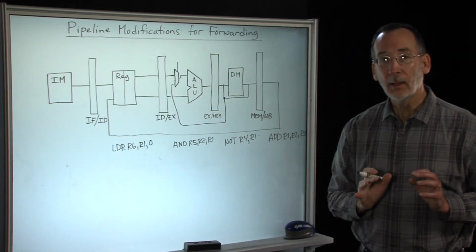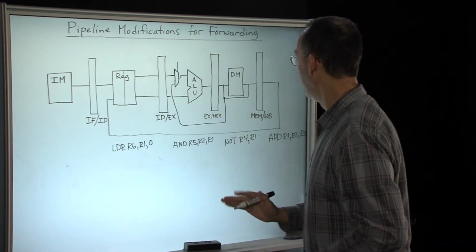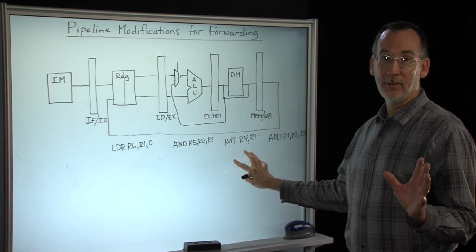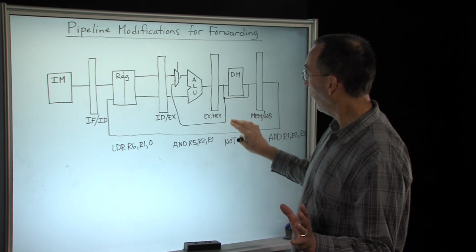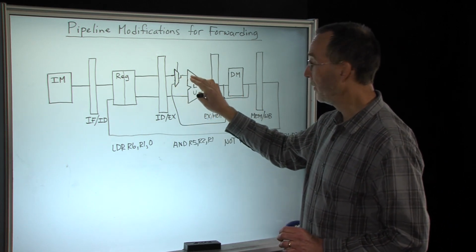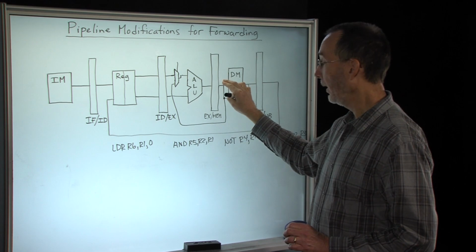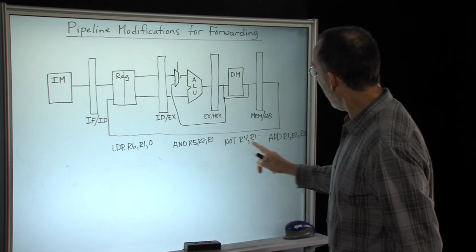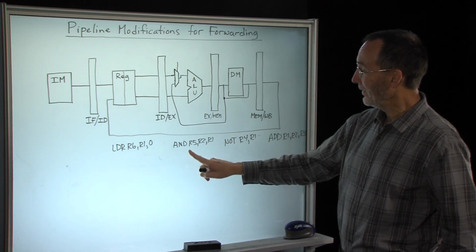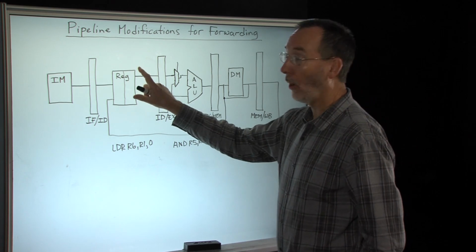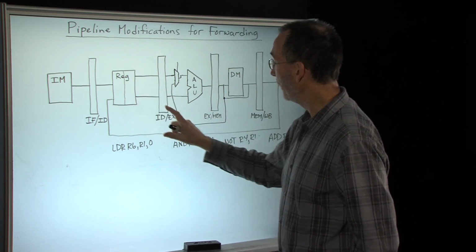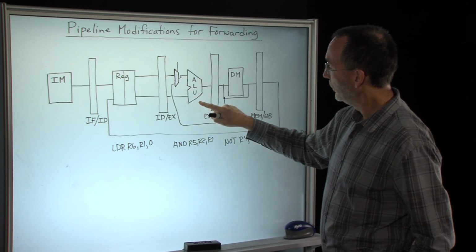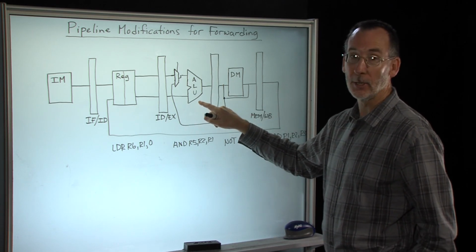Okay, so one tick of the clock later, this is the situation that we have. Now the NOT is all set because in the previous cycle we forwarded the correct value of R1, we've inverted that, and now that's sitting right here, so the NOT has been properly executed. But now we have the same problem with this AND. This AND has read an old value of R1 in the previous cycle. It's about to use that to do this ALU operation.